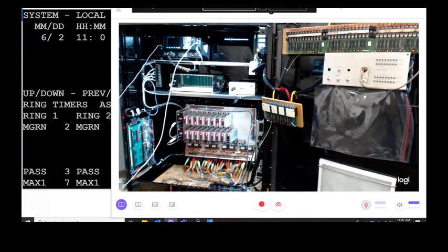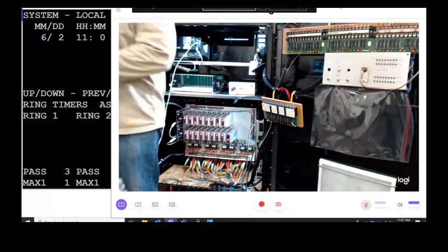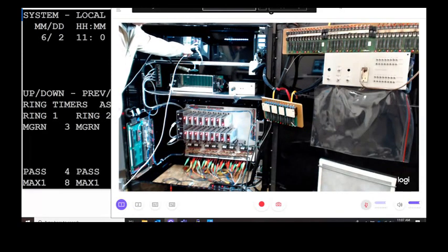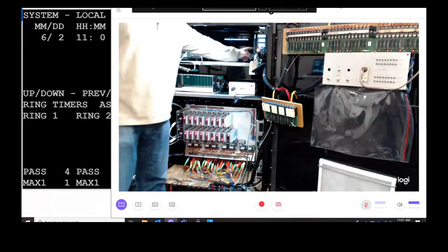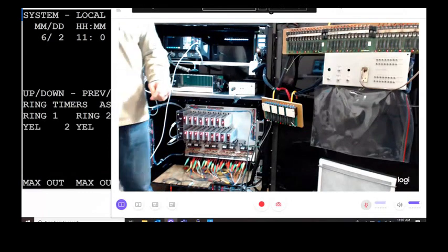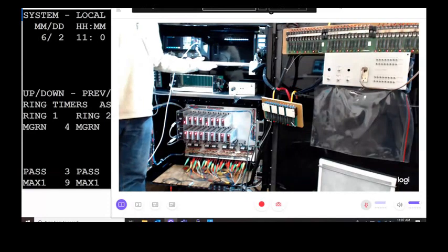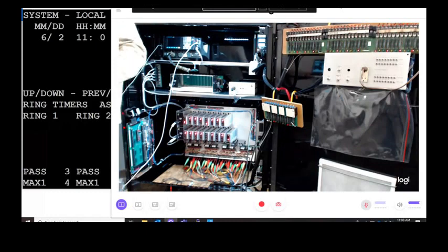All right, now here's another one that comes in all shapes and sizes. I did 2 examples of it. It's a port 1 fail. So port 1, we refer to port 1, all the SDLC cables, the port that they plug into is referred to as port 1. So I have a port 1 on my controller, I have a port 1 on my MMU. Okay, so when I have a port 1 fail, it generally means that I have an issue with the port 1, or I've lost communication to that port, so I'm going to generate a port 1 fail.